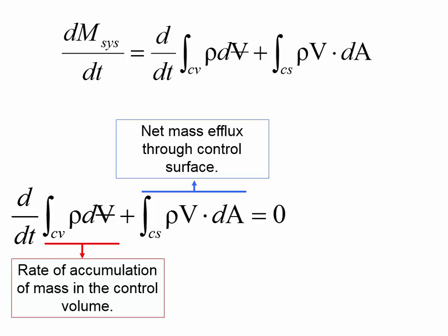And when we were looking at the system, we said that there was some flow into a tank. And so we just drew these imaginary lines, and the water level will either be falling or rising depending on the difference between the flow in and the flow out. And so Reynolds transport theorem is all about the calculation of where the mass is over time.